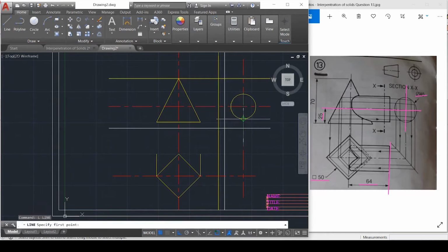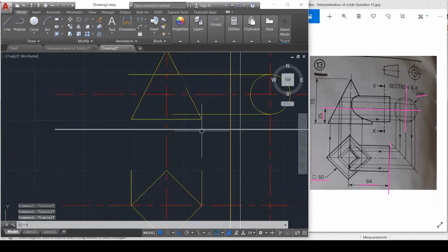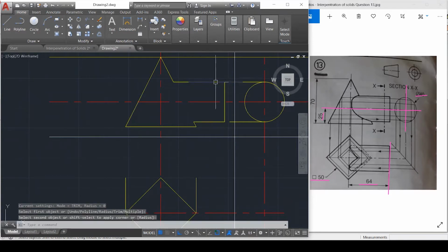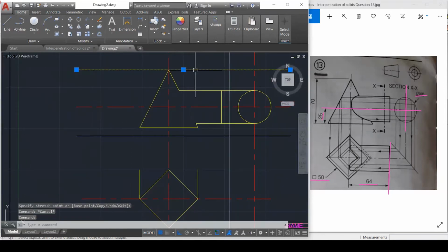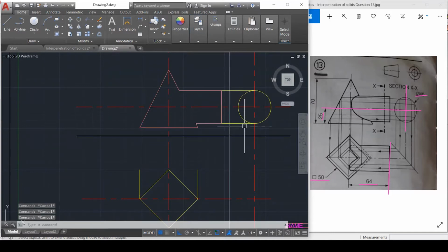So now let me just do this. Let me clean up this shape so that this shape is more understandable. Okay, so this is starting to look like the shape that is in our drawing to the left. So I'm breaking these lines here because these lines are going to be my outline, and I want these to be my construction lines that stop right here. So what I did is I just broke them so that when I put the shape into outline, those other lines would remain as construction, like what I'm doing now. Right, so that's outline, and the other lines there would remain as construction lines.